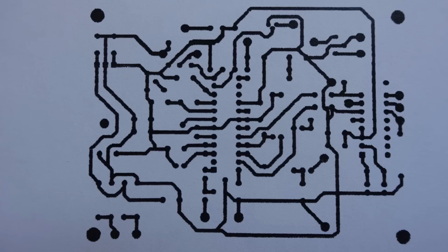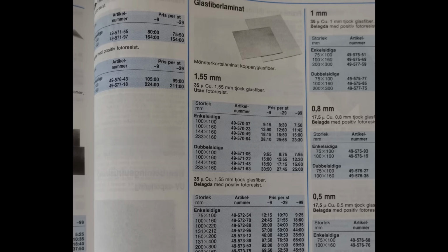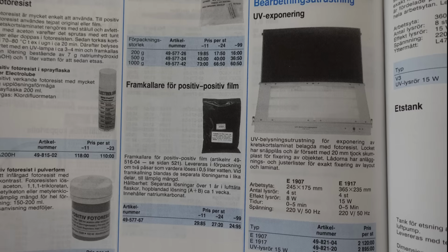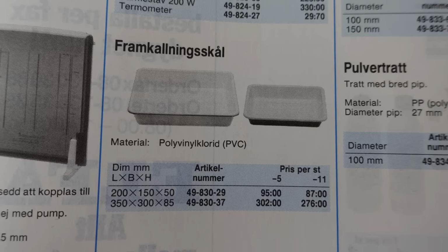If you were doing prototype PCBs back in the day, you'd probably have the following equipment. You start with a copper-clad board with photoresist on it. You put it in the UV exposure box with a mask you made in between for a few minutes. You then put the board in a tub with a weak lye solution, known as a developer. Photoresist that was exposed to light will come up with some gentle rubbing.